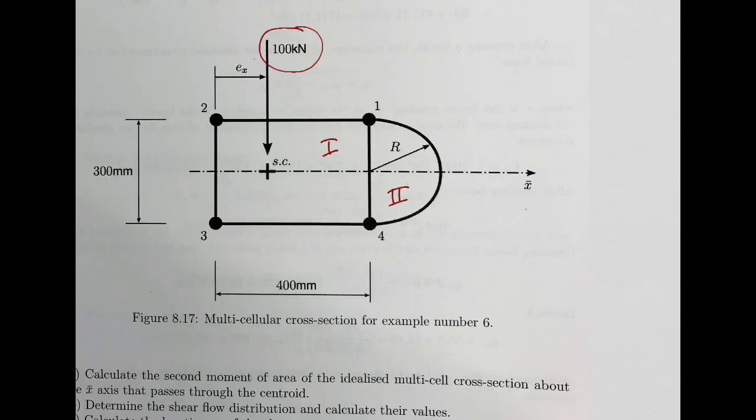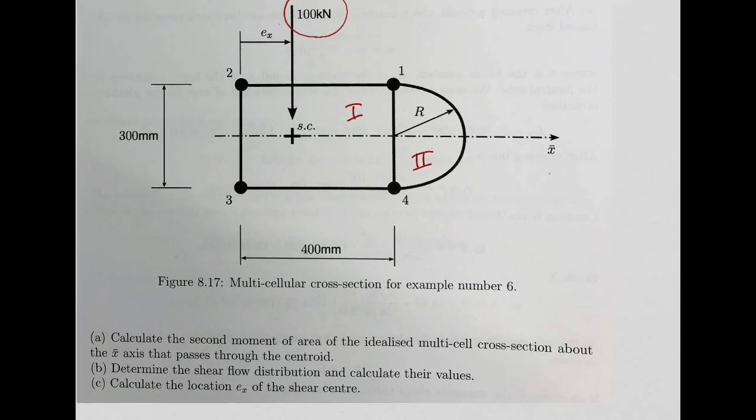So that's why when we design, for example, the wing box in a wing, one of the key things we need to bear in mind is the location of the shear center. Make sure the lift is acting as close as possible to the shear center. So I'm going to show you in this example how, from this transverse shear flow analysis we have been doing, we can quite easily get the location of this shear center. That is one of the questions.